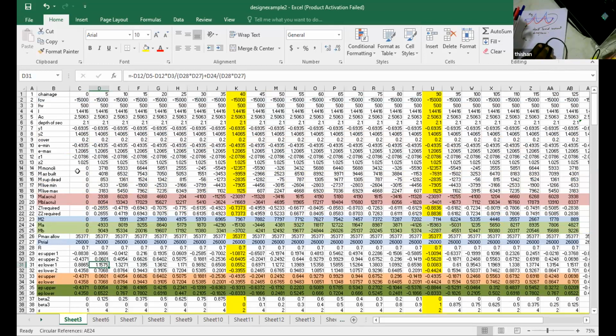Then when I calculated this MA, if you look at this diagram, you can see I have considered the monolithic diagram for MA. Just look at MB, you will find I have used the as-built diagram for MB. Why? Immediately after construction, what governs is the construction sequence-based one, that is as-built.